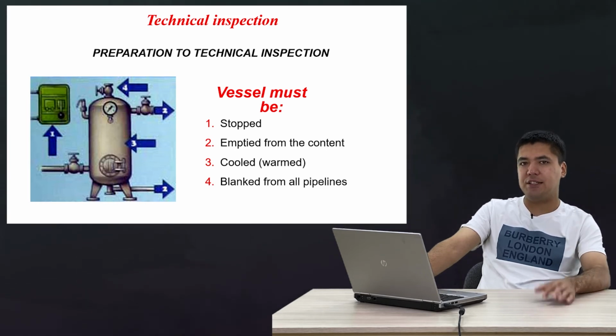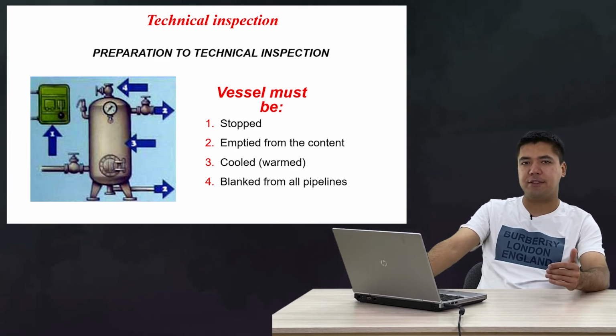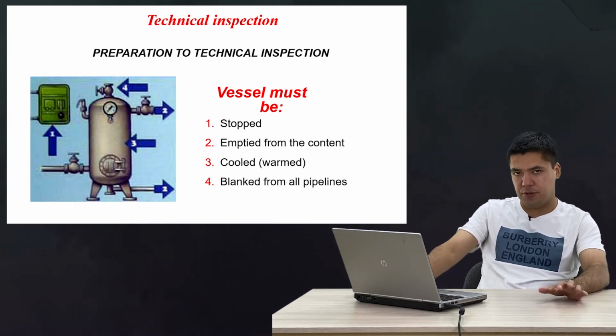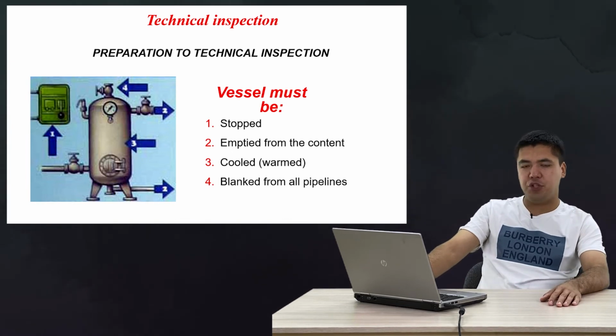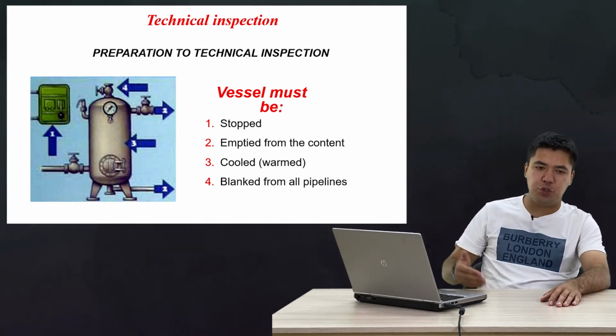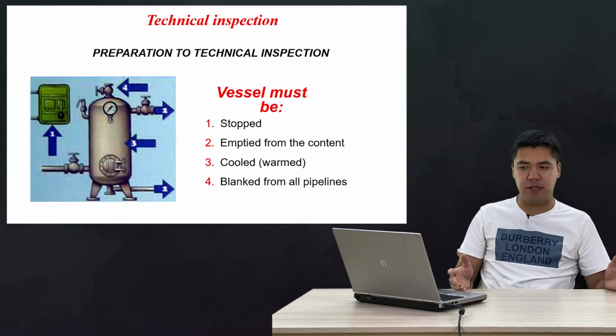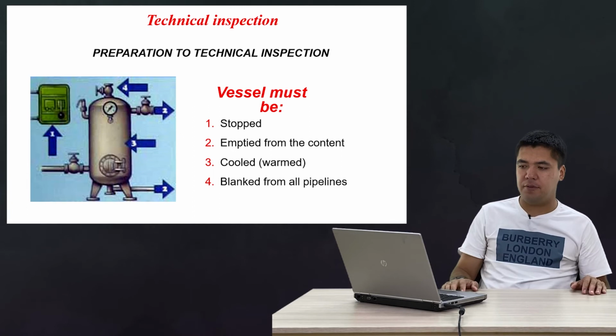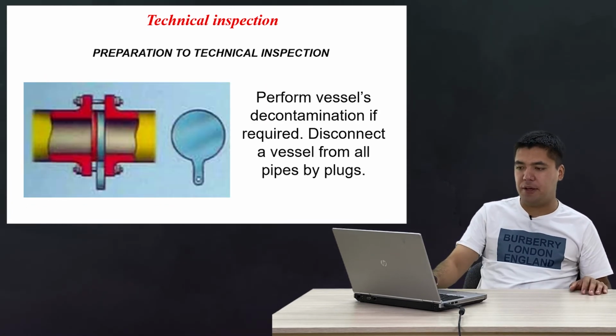We need to disconnect from all electrical lines. Also, we need to discharge all excessive energy like pressure of gas or liquid, doesn't matter. And we need to wait until our pressure equipment is fully cooled. Also, we need to check that all the pipelines, tubes, and connection details are blanked off from the gases and other environment in the pressure device.